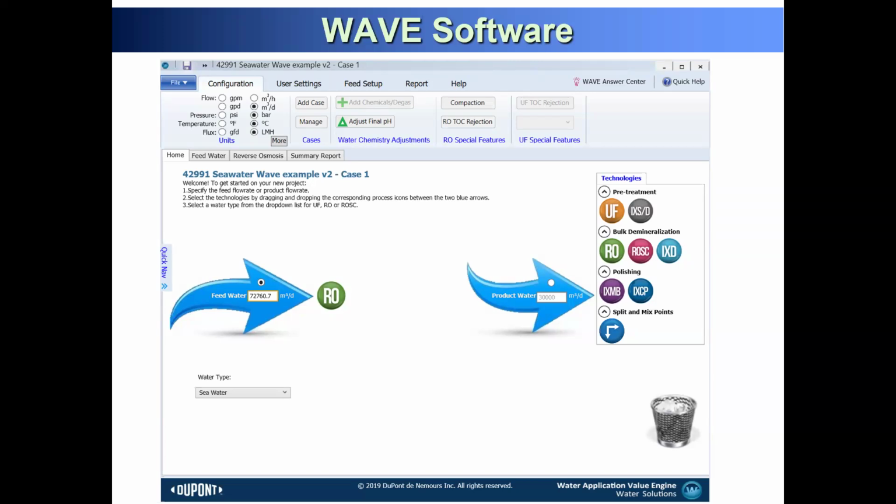You just fractionate, multiply by your fraction of the design, and then you can more easily calculate your design. So let's say you want to design 250 megaliters per day. I want to design 50 megaliters per day or 10 megaliters per day and multiply over 250. So here it's just one train design, not the whole capacity. This is one train, 10 megaliters per day or 1 megaliter per day. So you design only a small part of your membrane system.